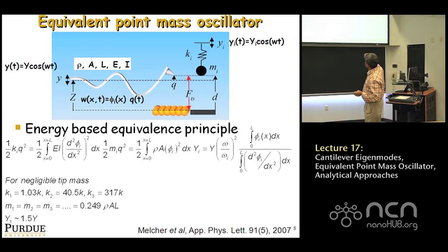And what you see out here is, let us say, can someone tell me which mode number this beam is vibrating in? How many nodes do you see? You see 3 nodes. So this must be the 4th eigenmode. Okay? So let's say the cantilever is vibrating in the 4th eigenmode. And this is a true eigenmode shape, right? Where the tip moves up and down Q. Q is the motion of the tip, actual deflection of the tip in nanometers. But you see this thing really wiggling in the 4th mode. The base is being shaken by an amount Y.